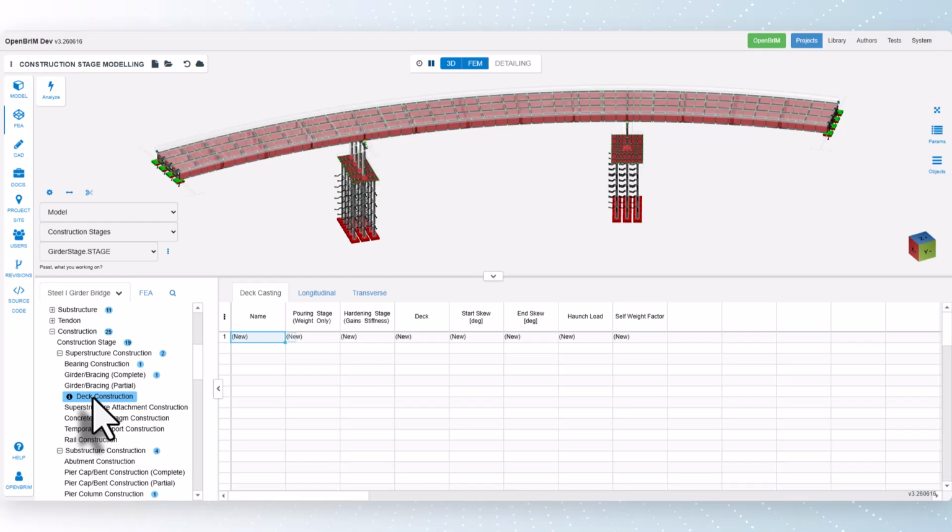In our model, we will define the deck object in 5 stages. For typically sized bridges, the most common placement sequence involves pouring the positive bending moment regions first, followed by the negative moment zones. The positive moment zone pour is typically defined as being between points of dead load contraflexure. After the positive moment zones have sufficiently cured, usually several days, the concrete for the deck in the negative moment regions is poured. This technique of using separate pours aims to minimize deck cracking over the piers. Most of the girder rotations at the bearings occur when the concrete in the positive zones is placed.